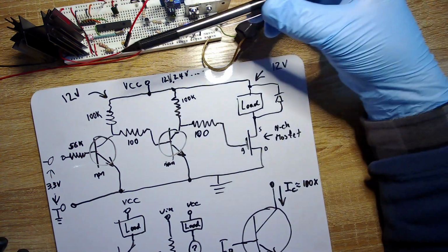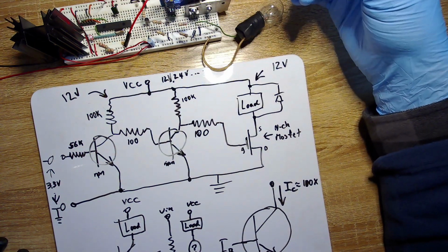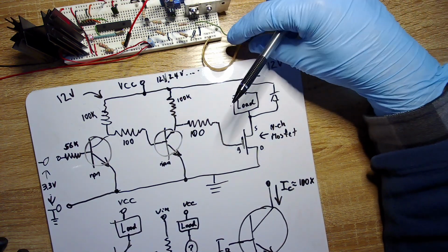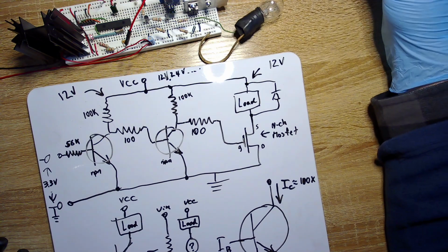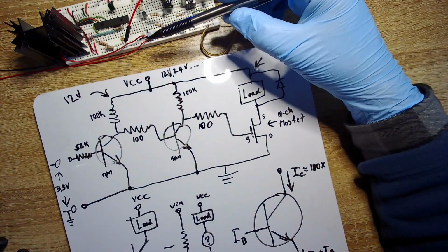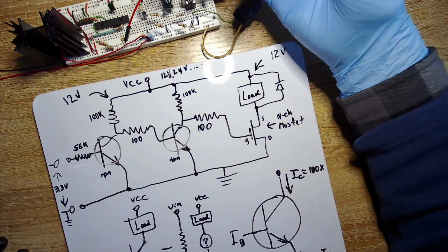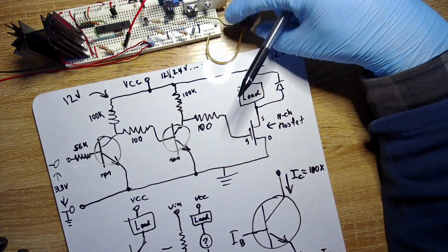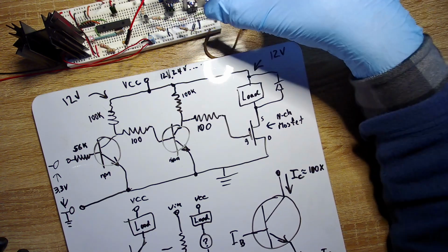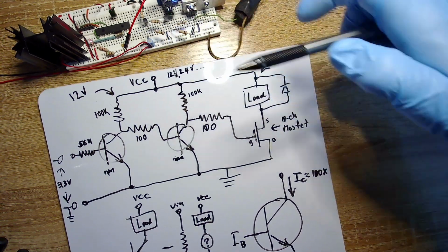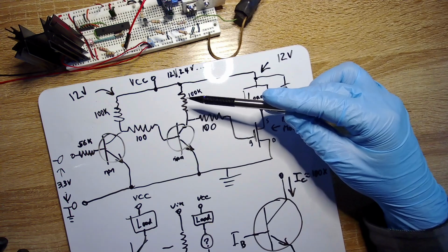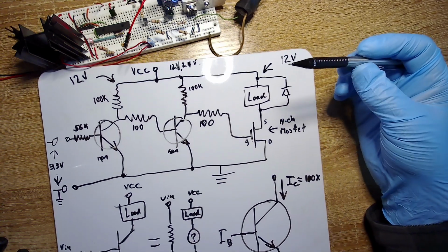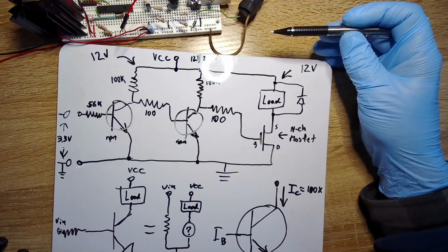What was my point mentioning the 5 volts? Okay, now I forgot what my point was in mentioning that voltage regulator. With capacitors on the board, what you'll find is when you put noisy things like computers on the board, the voltage regulators absolutely need the right capacitance there in order to regulate the voltage. That's what I was trying to say. This seems to be working just fine without any sort of coupling capacitors or anything like that.